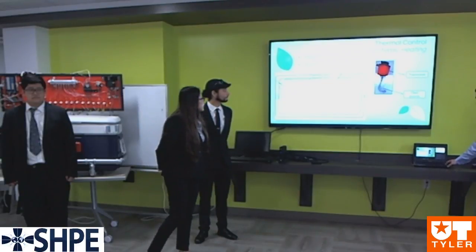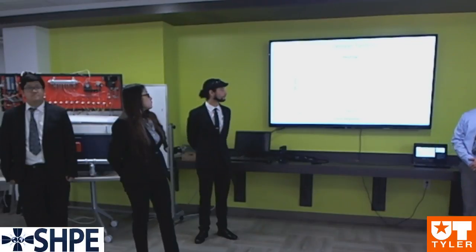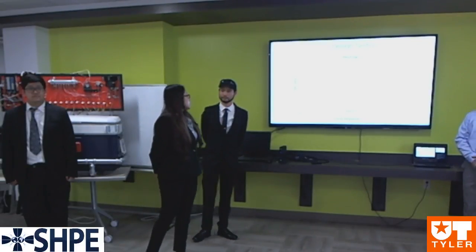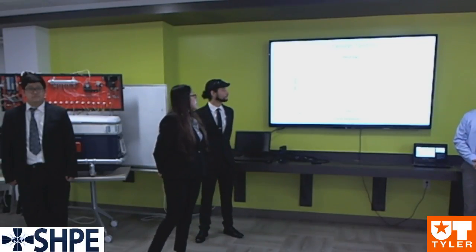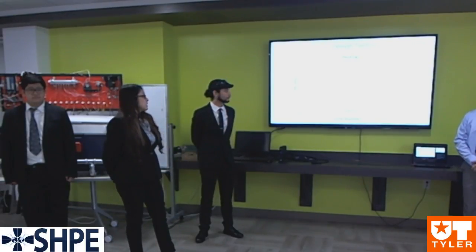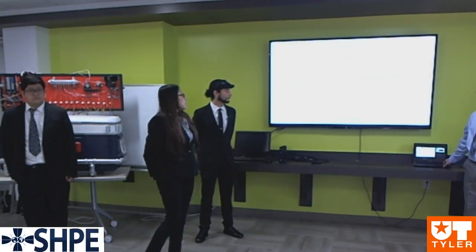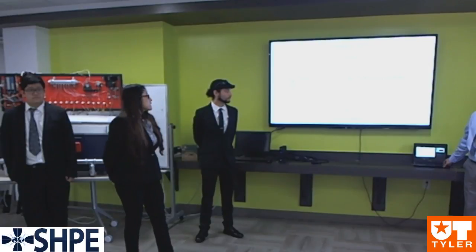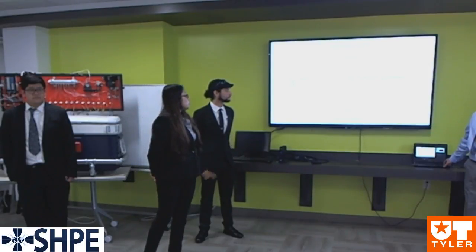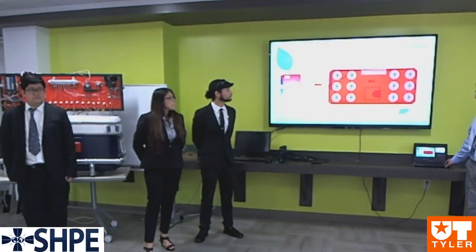Our graph here shows our initial response at approximately 250 minutes. It shows the system being at equilibrium at 60 degrees Celsius with a constant temperature for the heating of the system. At launch stability, you can see for the 1200 minutes that we tested that it was constantly at 60 degrees Celsius throughout the whole time, which proves that our requirement for the thermal control system was met. All right, thank you.